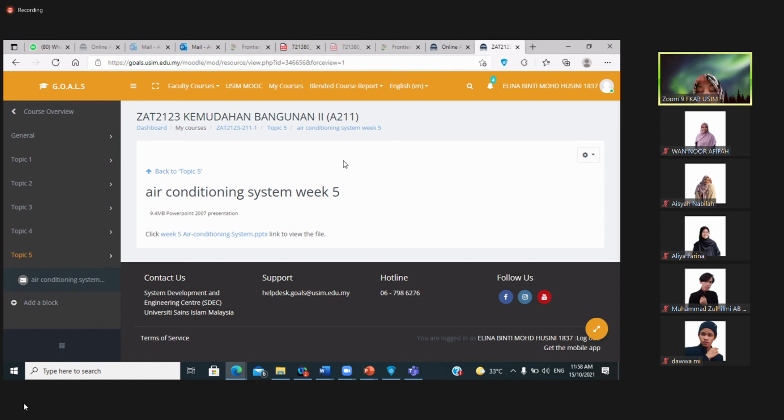What is the height of the floor area? What is the architectural vocabulary on the technical side? Floor height, clear ceiling height. Clear ceiling height means the height after your ducting, from ceiling to floor finish level. What is floor finish level? That's it.